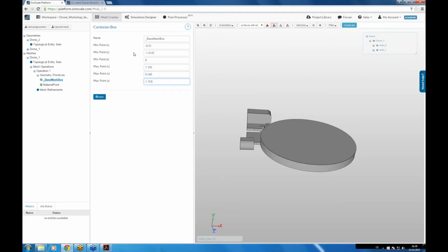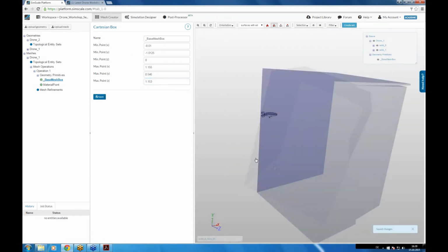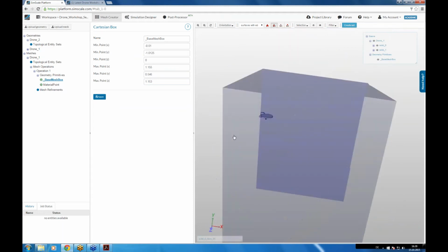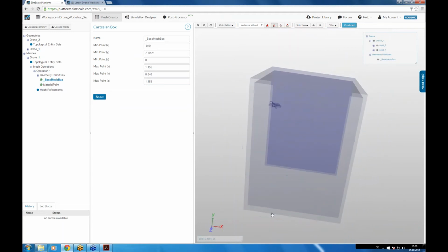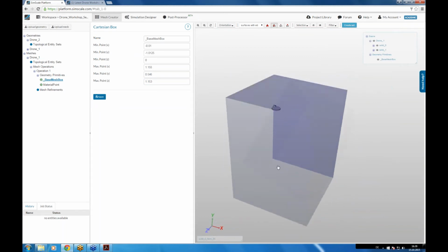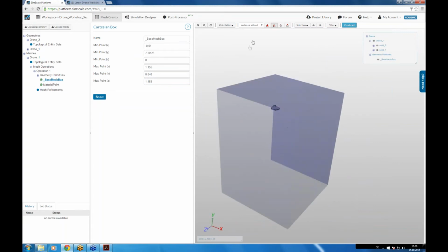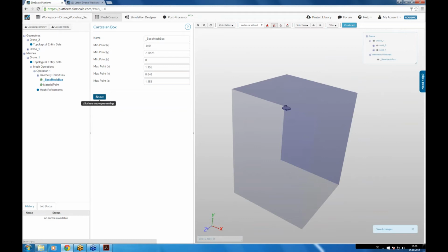If you want to do the simulation yourself, what I am doing here is I'm creating this box first in my CAD model, and then I can extract these points from the CAD model. And now you can see this is our box, which we will use now for the simulation. This is a little bit bigger than on the slide, because we want really to avoid interactions between the flow and this wall. Okay, confirm with save.